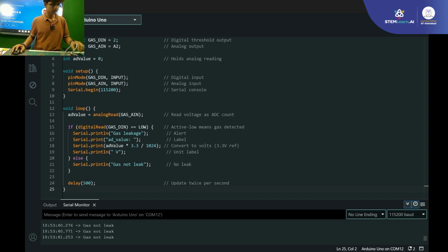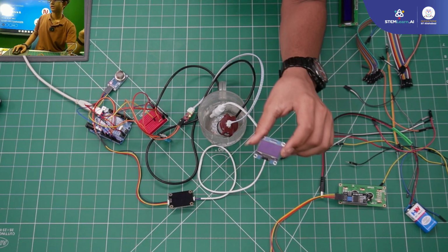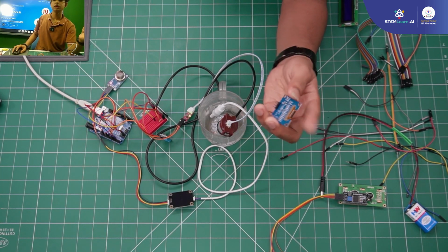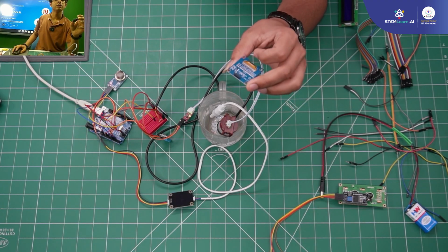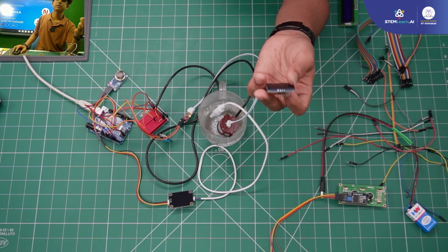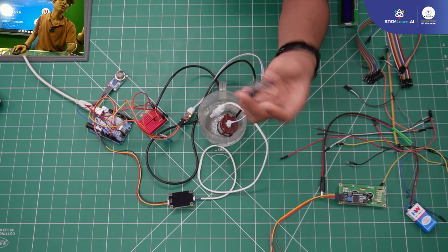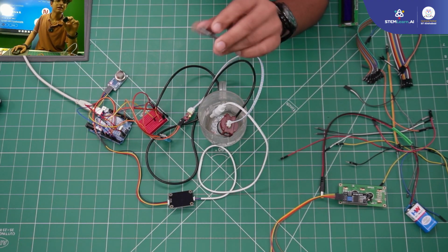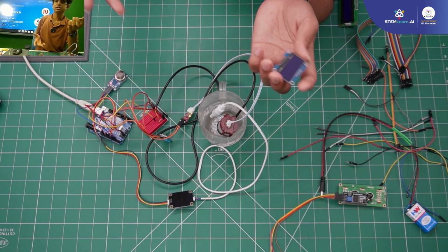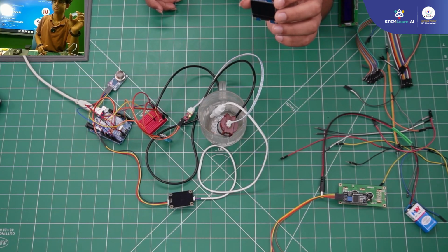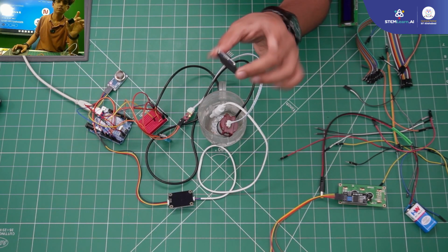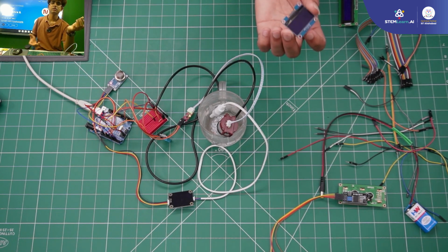Now we are here. Now we need to go to our OLED display. So what we'll do is we'll print all these values on our OLED display. Let's go to hand cam. See, this right here is the OLED display. It is the same I2C, but it just requires a different library, that is U8G2. So if you use just that library, I've already given it in the GitHub, so you can just copy it from there. Otherwise I have given the description links also, on how to download.